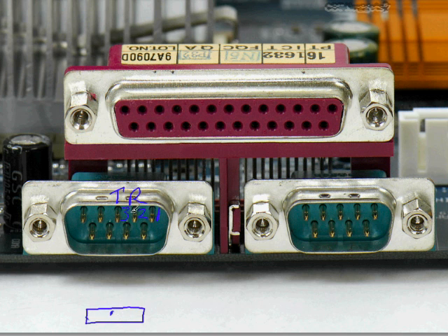We would have two pins that were set to transmit, and I would never be able to receive the data. So what happens here is, in the cable itself, it crosses over to pin 2 instead. Pin 2 here, pin 3 here. And then on the receiving end, it would cross over and connect to pin 3. So there's a crossover that takes place directly inside that cable, allowing a null modem transfer to happen.